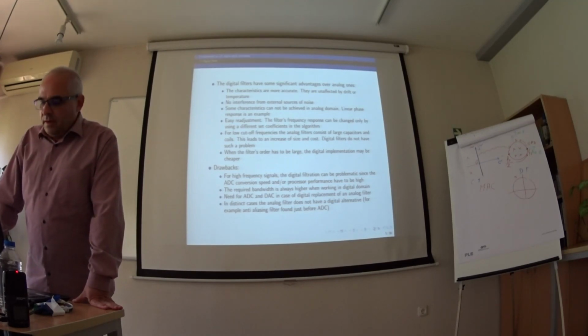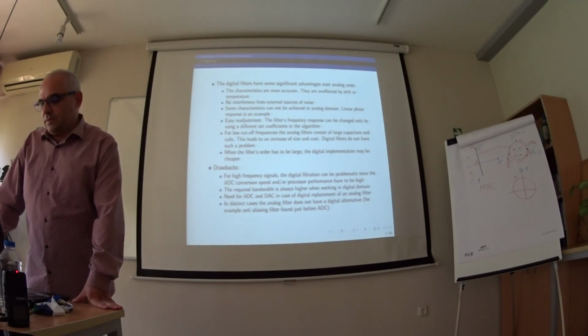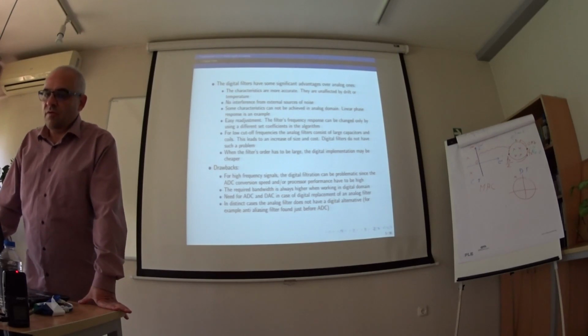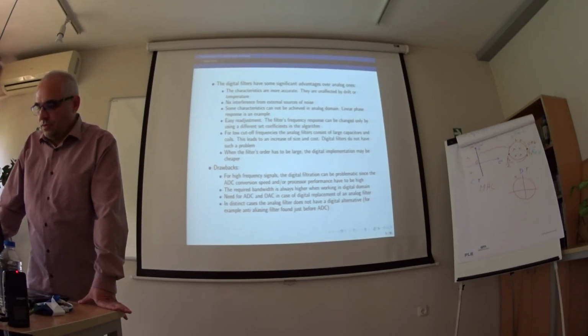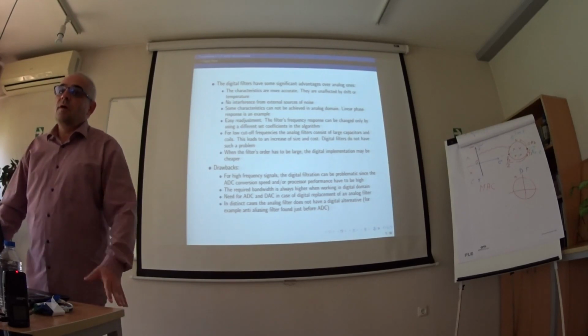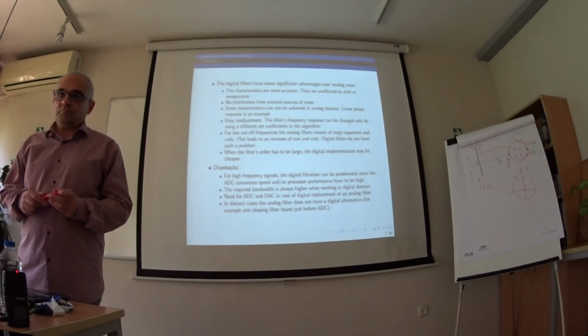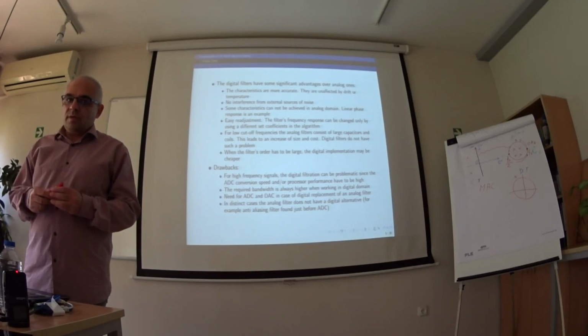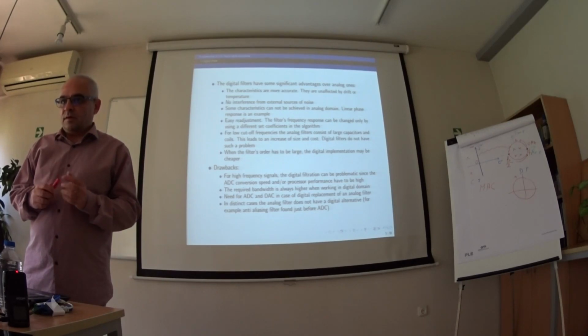We can make our digital filters just in software, and we can change the coefficients. So by changing the filter's coefficients, we can readjust the filter behavior very easily and very quickly. If we have an analog circuit with analog elements, if we want to make a high pass filter from low pass, we have to change the interconnections, which is not very convenient. In our software realizations of digital filter, it is quite easy.